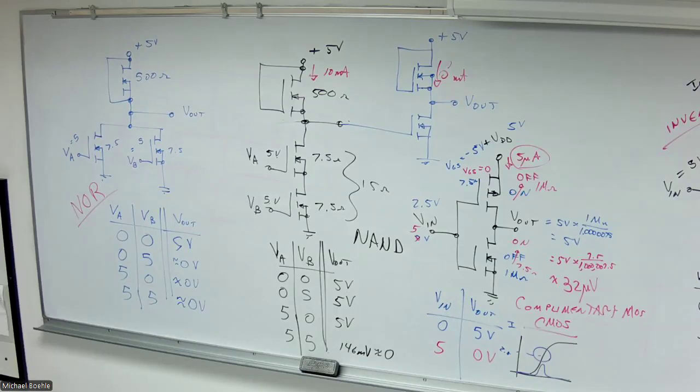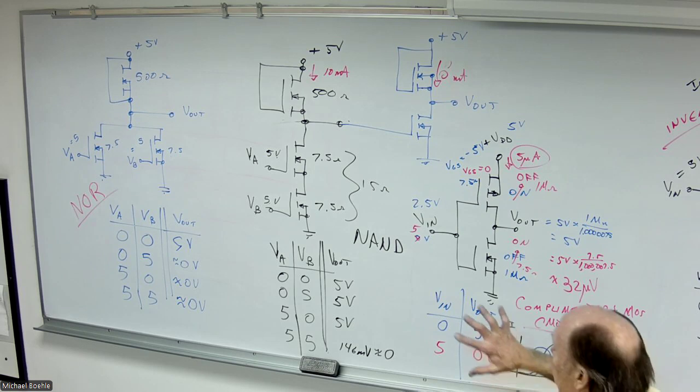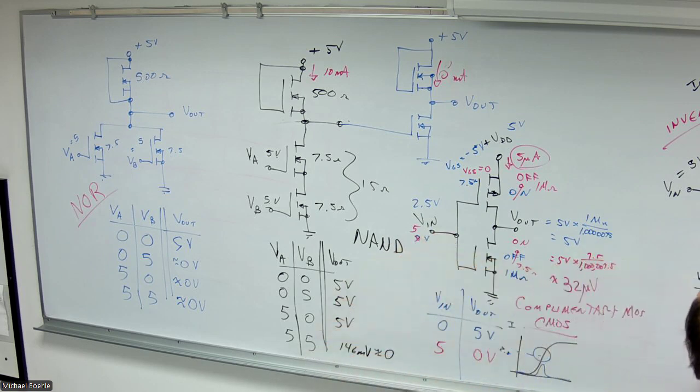Now, the last part of this chapter gets into power field effect transistors. All we're talking about with a power field effect transistor is just a device that can handle higher currents or higher powers, right? They're put into larger structures that can dissipate the heat that is produced. It may also include an internal diode that is reverse biased during normal operation. And there are a few advantages of field effect transistors that are especially useful in power configurations.